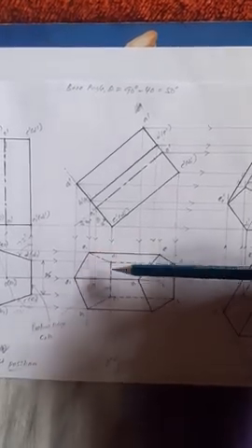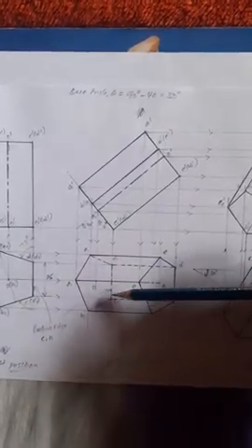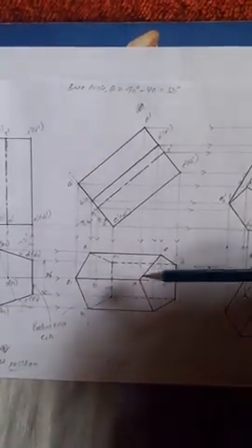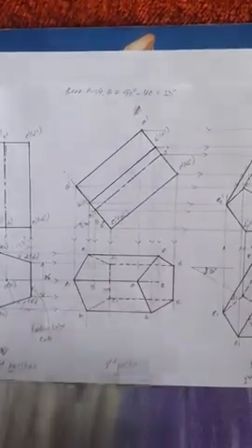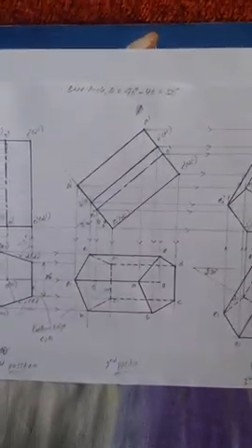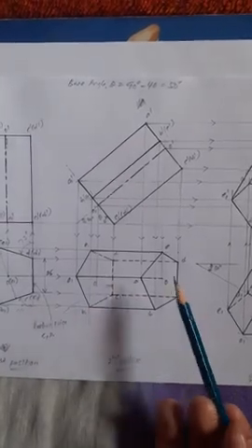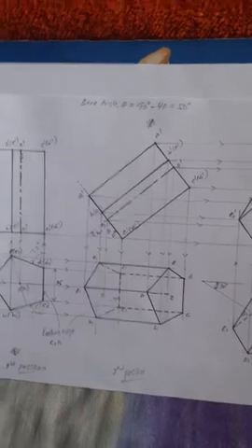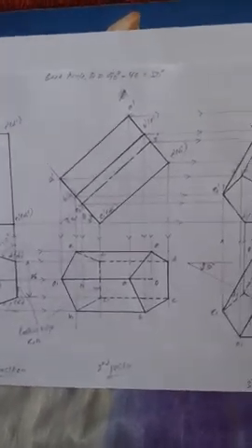D1, E1 edge is there. C1, B1 also an edge is there. That is a dashed thick line. Similarly D1, D rectangular face edge, and C1, C also a rectangular face edge. Those are also dashed thick lines. Then O1, O is the axis line, but that coincides with A and A1. That completes the second position, top view, right?